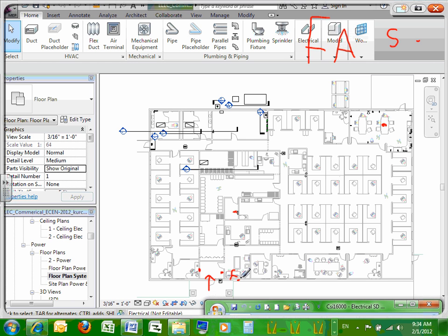Manual pull stations at exterior doors. Again, they're not required, and especially with us doing a lot of schools, they used to require them in schools. Now, for obvious reasons, they don't require them in schools because people would pull the fire alarm a lot. In fact, most fire marshals will tell you to get rid of them right now if you have them, because more false alarms in a school means a lot of wasted time for them.